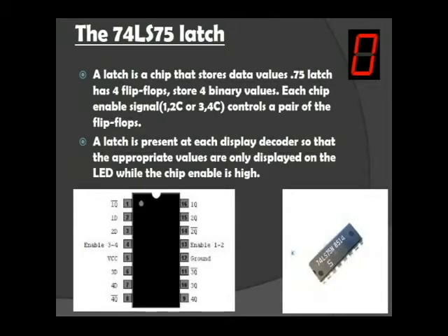The 74LS75 latch. A latch is a chip that stores data values. The 75 latch has 4 flip-flops, which store 4 binary values. Each chip enable signal controls a pair of the flip-flops. A latch is present at each display decoder so that the appropriate values are only displayed on the LED while the chip enable is high.